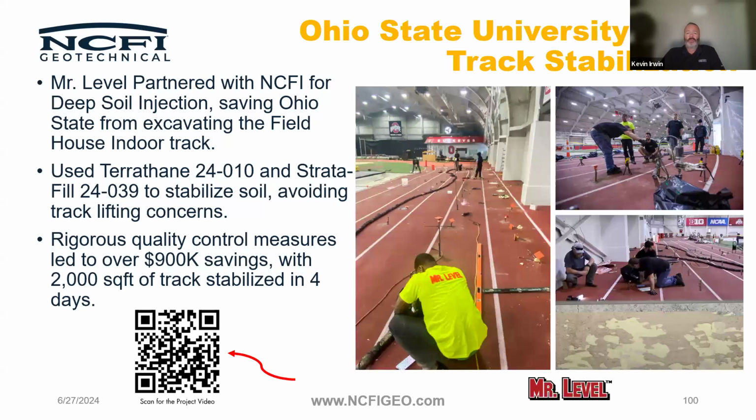The indoor track needed to be stabilized. They used 2 different systems: Polyurethanes 24-010, which is a fast system, for the shallower injections, and Stratafill, our Stratafill line 24039, which is a very slow system. It's also hydrophobic to stabilize soils.